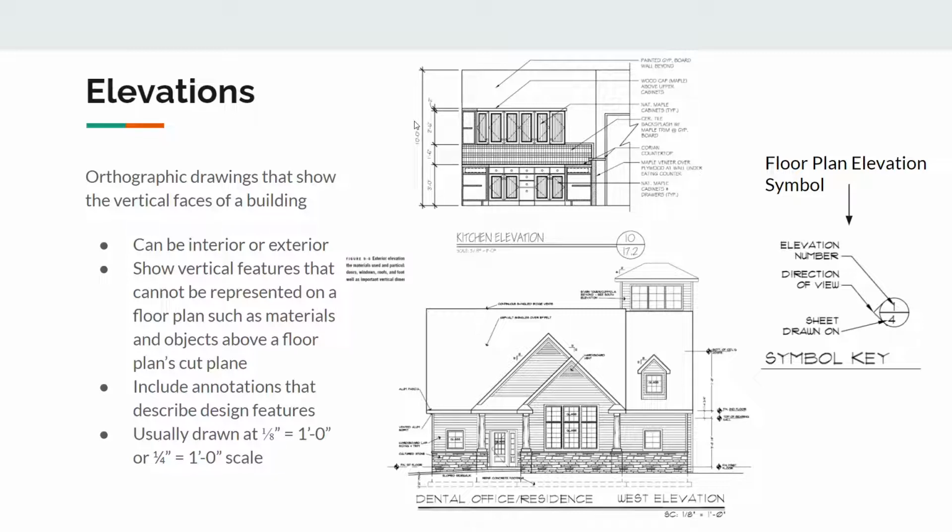Okay, and this is going to be consistent on elevation drawings and any plan drawings you're doing. You're always going to want to show these dimension strings of all the individual dimensions, and then you want to provide overall dimensions. All right, and whenever we're dimensioning, we're going to be dimensioning from a consistent point typically. So on a floor plan, every dimension is usually from maybe the right side of one face of a wall to the right side of the next face of the wall, or it could be the left side. Whatever it is, it needs to be consistent.